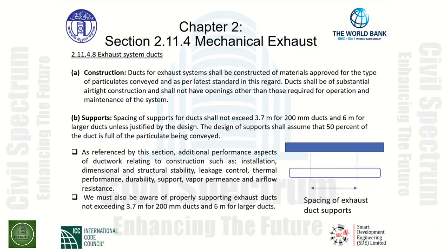We must also be aware of properly supporting the exhaust ducts, not exceeding 3.7 meters for 200 millimeter ducts and 6 meters for larger ducts.